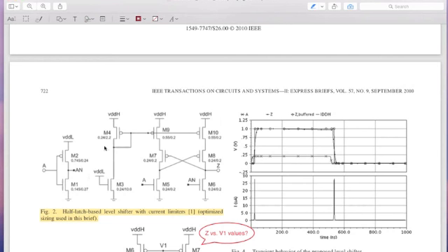So you have a current here generated, diode connected PMOS, which supplies a voltage to these two gates. So this voltage will be not ground, somewhere in between, and that reduces the currents which can come from here. So once I limit the current which can come through the PMOS, that is what I want. I want to limit the current through the PMOS so that NMOS can overcome that current when it's on. So this is the approach with which they contrast.